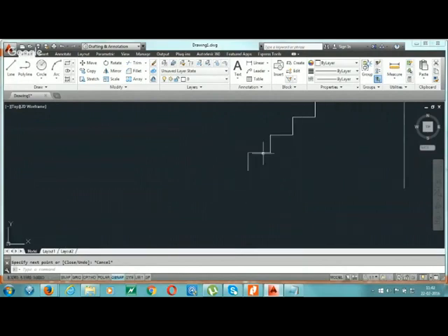We need one more corner in here. Then go to the line command, with the help of snap take this point and go to the syntax @ with the help of shift, at the rate minus 0.45 comma 0 and go downward at the rate 0 comma 0.35. Enter.